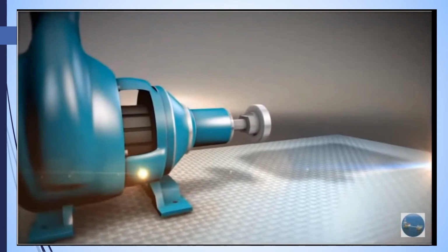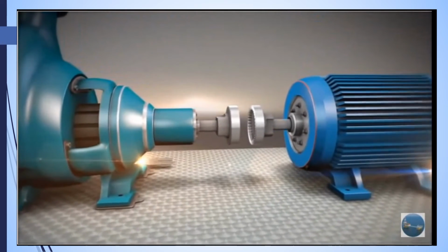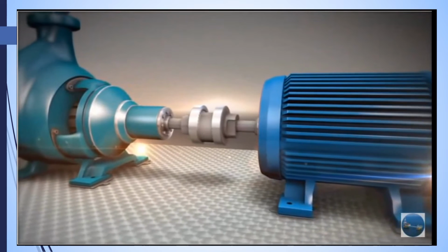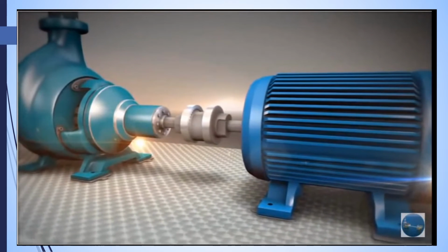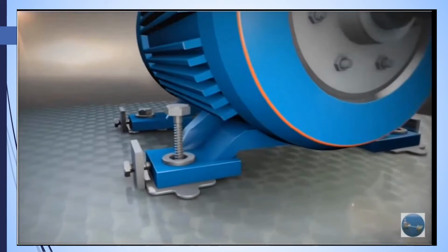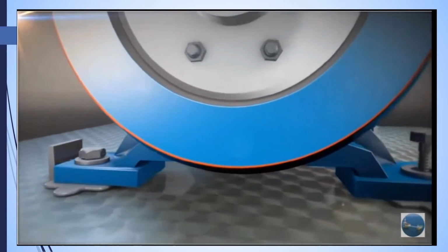With the base plate in place, the rotating equipment should be centered horizontally upon it and an equal amount of shims placed under each foot, while keeping the required axial gap. Installing jack bolts is also recommended to facilitate horizontal movement of the machines. Finally, all anchor bolts on the machines should be tightened to the proper torque.